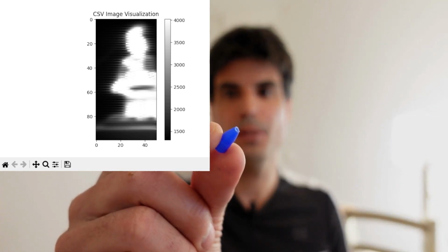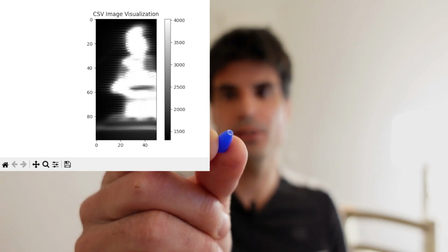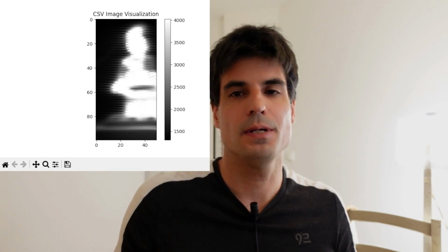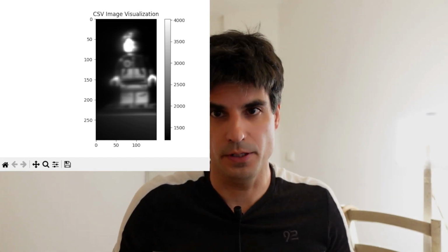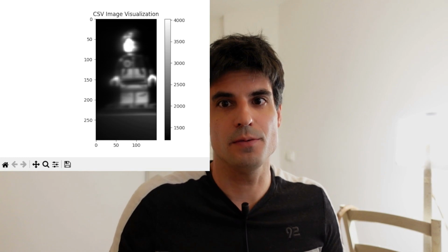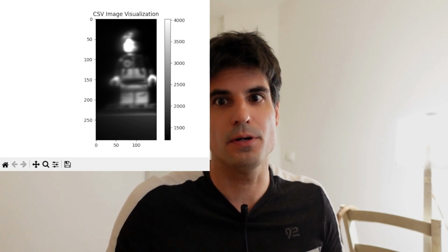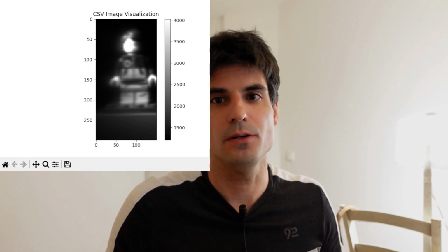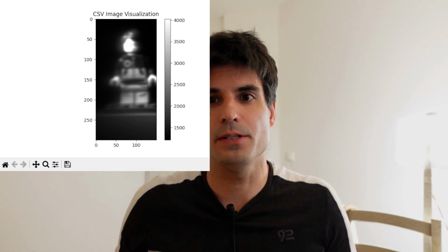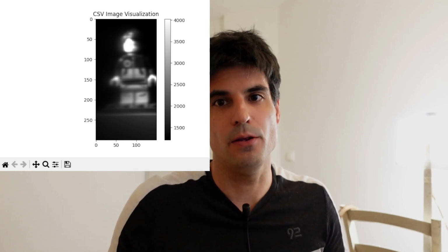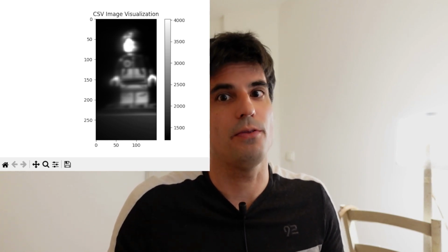So for the next step, I tried to make the aperture on the LED smaller, and I've also lowered the step. I made the step of the stepper motor smaller to increase resolution. And this is the result. It's much better. You can see some features like the zipper and the patch on the shirt. The face is a little burnt out, so we have a very low dynamic range, but who would have thought?